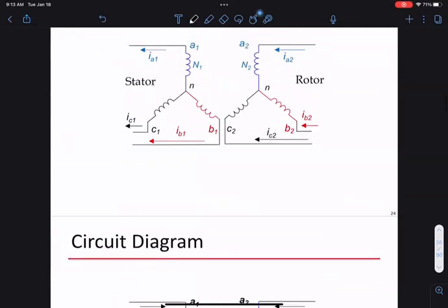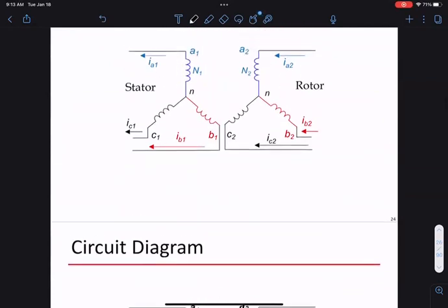So what happens when you study this is there are three inductors on each side. Now, how many couplings are there? What is the number of different relationships we have? There are 3 by 3, 9 different couplings, because each inductor on one side will couple to any of the 3 on the other side.